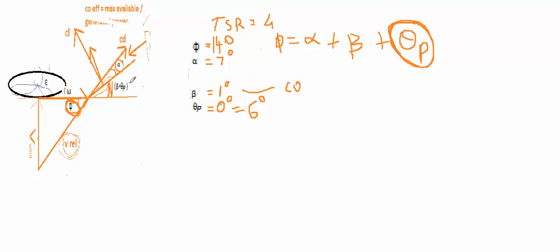So to compensate for the change in the angle phi, because beta is the twist angle which we have already designed and it can't be changed, we put a mechanism to change the complete angle of the blade, which we call the pitch angle. So this is the concept of the pitch angle.